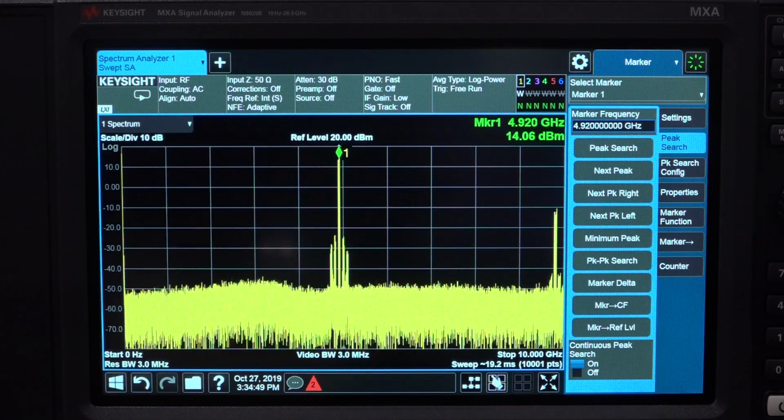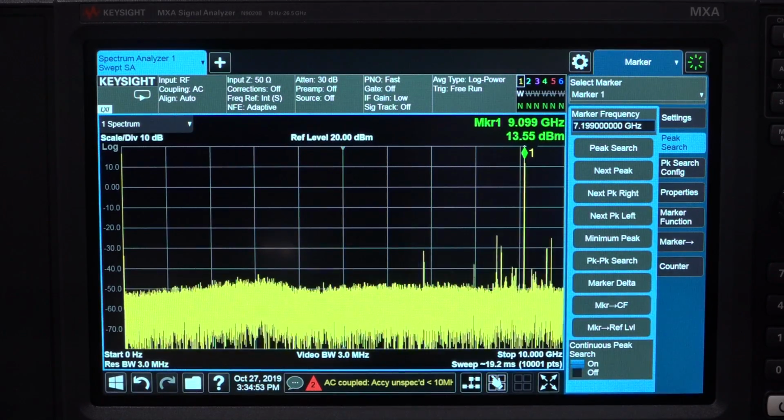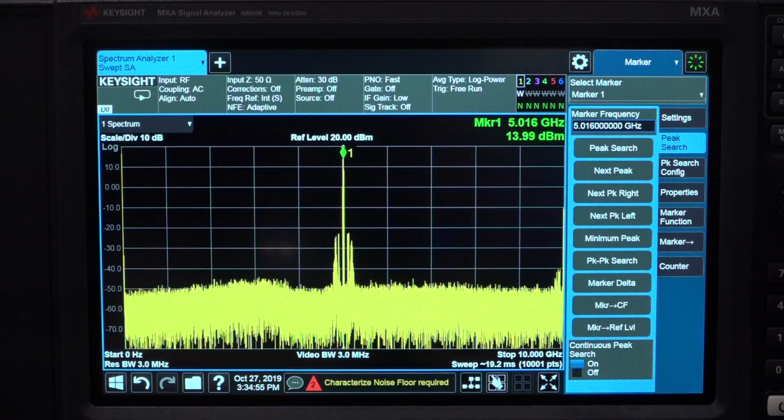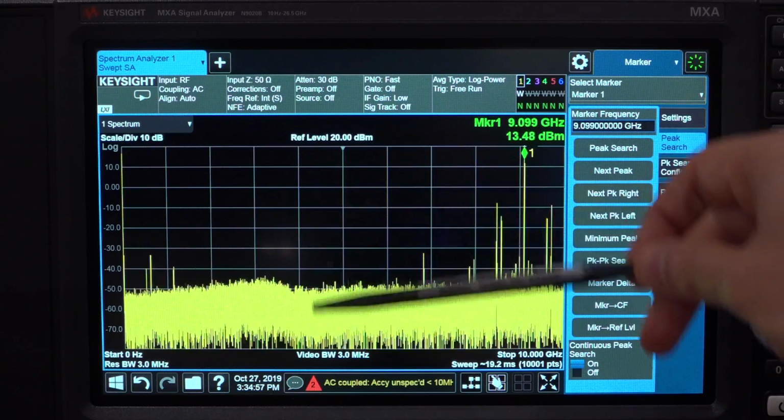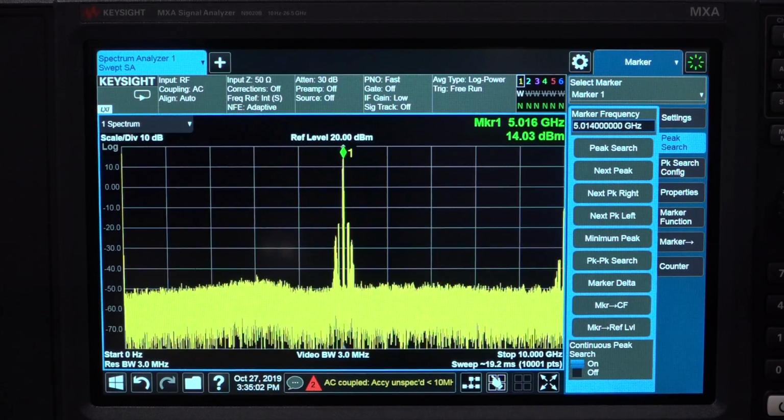Yeah, this might be out. Okay, there you go. Now it's not working anymore. Yeah, it's not moving. There it is. It just lost it. So, yep, indeed, you can see that it cannot decide where to keep the frequency. These spurs that are appearing outside of the PLL band are not good. It means it's going in and out of lock.